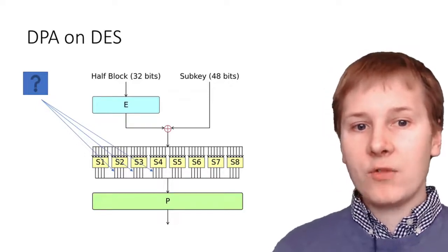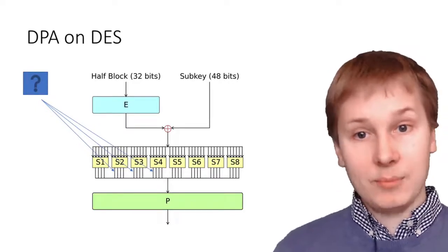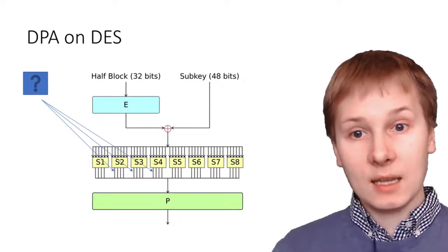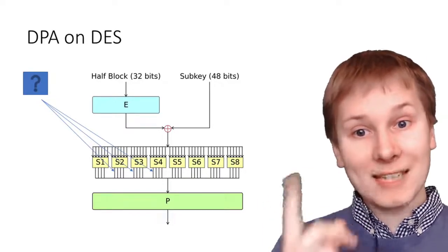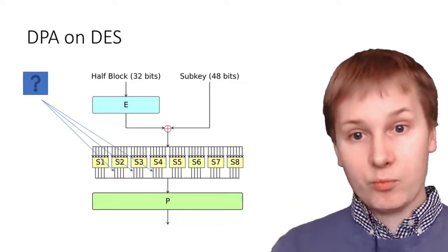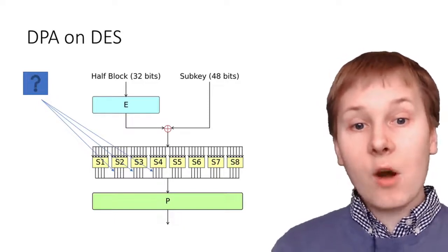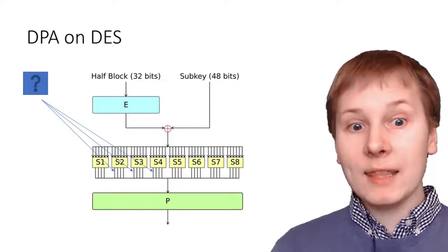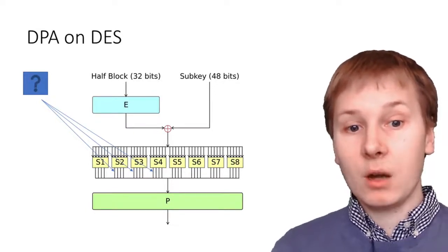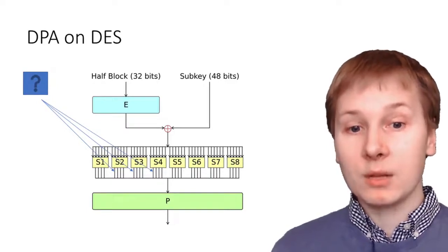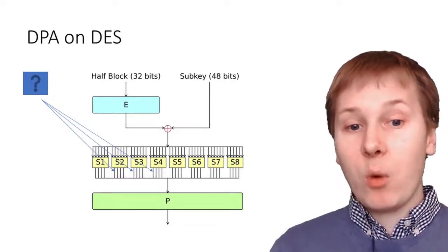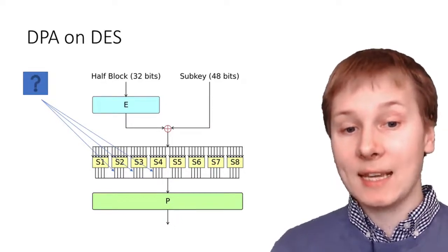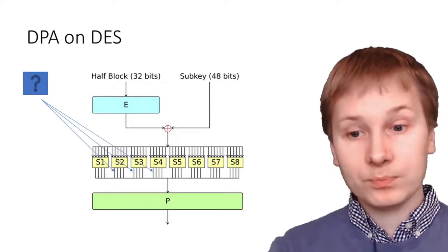And you can do the same in reverse with just knowing ciphertext and power traces on the last round of DES rather than the first round of DES. So all you need is the plaintext power trace pairs or the ciphertext power trace pairs, and you've broken the algorithm. Though there are countermeasures available based around limiting the correlation between repeat runs, ultimately the attack generalizes to many devices that aren't as well protected as today's smart cards. In 2016, there was a demonstration of a worm that could take over Philips Hue lamps by extracting the shared AES key used by every lamp to authenticate updates.